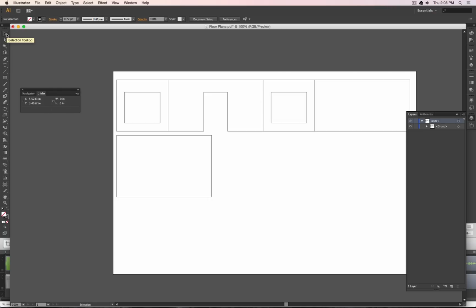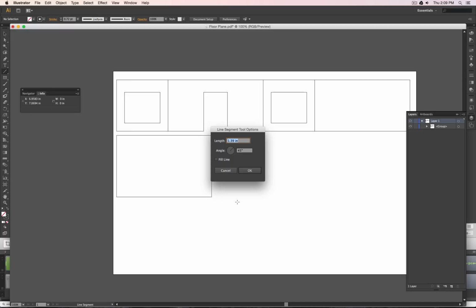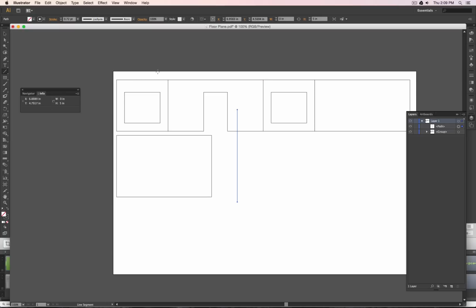Yeah, that's for example not a bad size. It's still maybe a little bit small. Maybe I would like this one to be like 5 inches. So I can go to the line segment, click somewhere. So I just mouse click, type in 5 inches, angle 0, okay, then 90, okay, good. So now this is kind of like the height reference of how high something should be.